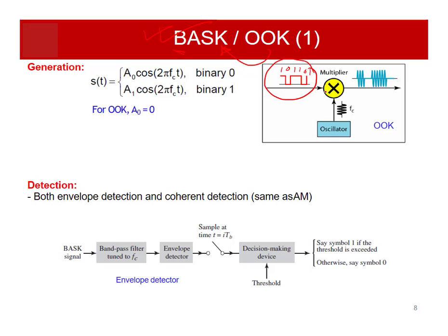So the amplitude shift keying modulation process is very simple. You have a multiplier block and you are multiplying this physically realizable signal of the digital bit sequence by a cos wave or a sine wave of a particular frequency fc. So this is basically OOK. Let me just explain this with the diagram.